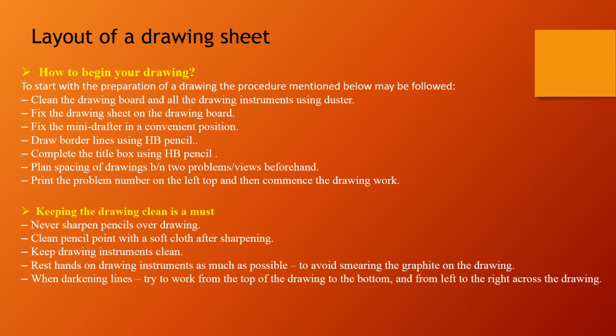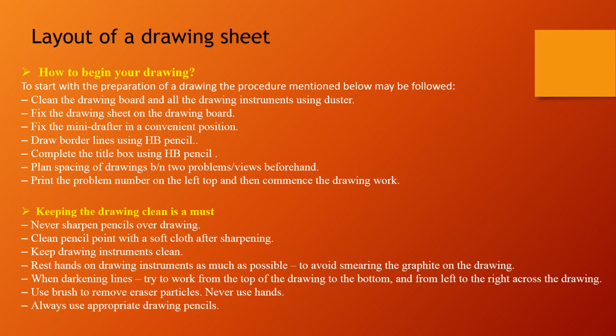When darkening lines, try to work from the top of the drawing to the bottom and from left to right across the drawing. Use a brush to remove eraser particles. Never use your hand. Always use an appropriate drawing pencil.